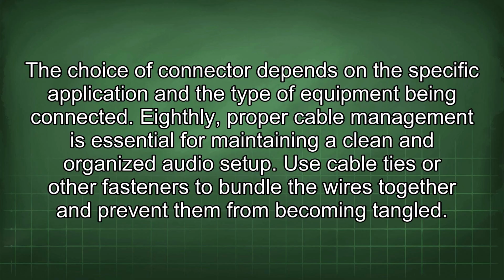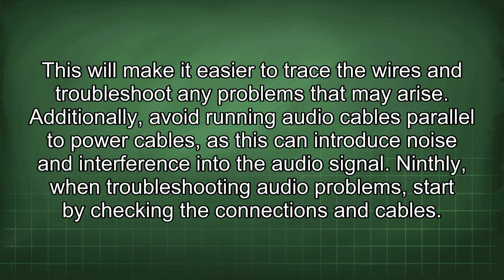Eighthly, proper cable management is essential for maintaining a clean and organized audio setup. Use cable ties or other fasteners to bundle the wires together and prevent them from becoming tangled. This will make it easier to trace the wires and troubleshoot any problems that may arise. Additionally, avoid running audio cables parallel to power cables, as this can introduce noise and interference into the audio signal.